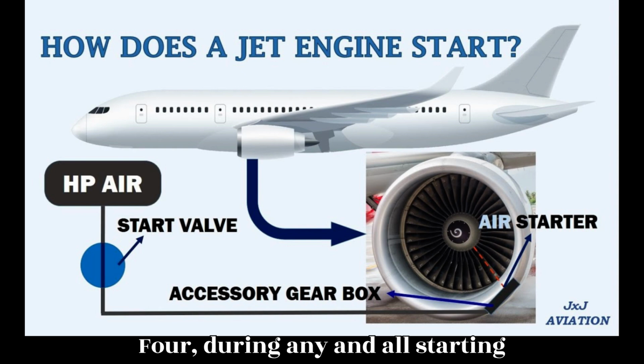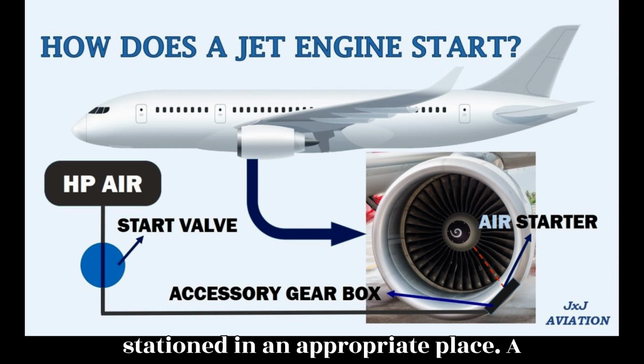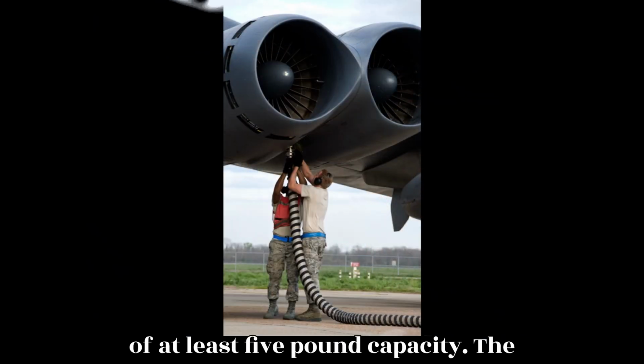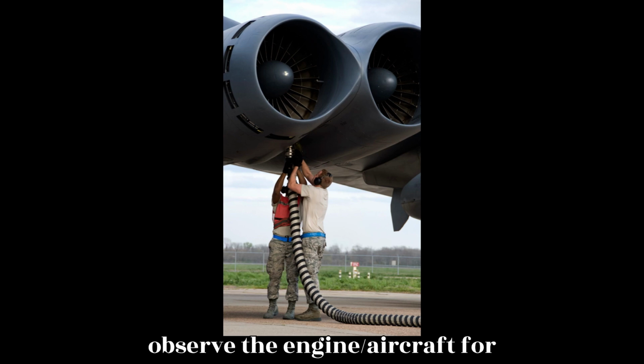4. During any and all starting procedures, a fire guard equipped with a suitable fire extinguisher shall be stationed in an appropriate place. A fire guard is someone familiar with aircraft starting procedures. The fire extinguisher should be a CO2 extinguisher of at least 5-pound capacity. The appropriate place is adjacent to the outboard side of the engine, in view of the pilot, and also where they can observe the engine/aircraft for indication of starting problems.